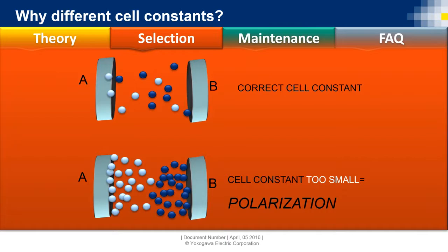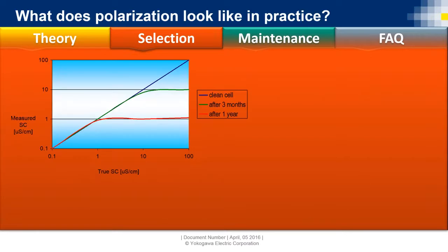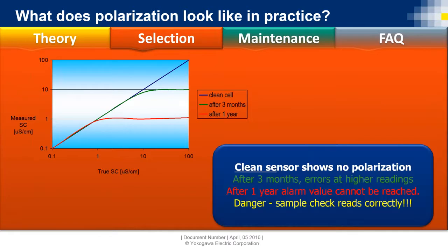So just be cautious, when you go to find a new sensor, that you don't just go, okay, I need one that's got a 2.0 and a 3/4 inch connection. Make sure that you know that your 2.0 is actually this measurement range. Or you could fall into a trap where you get a sensor that someone else's 2.0 is not 0 to 2000, but it only measures 0 to 400. You're actually measuring at 800, and then you have polarization that takes effect in your sensor. So just be conscientious of that.